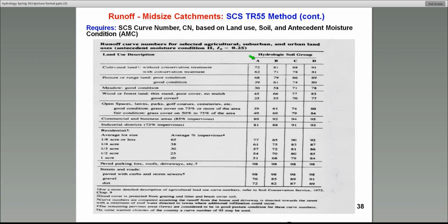A to D. The runoff coefficient increases, the curve number increases, indicating that there'll be more runoff, obviously, and less infiltration. So a higher curve number, more the runoff. You also have, for example, I will talk about this. There's a footnote here that becomes very important.